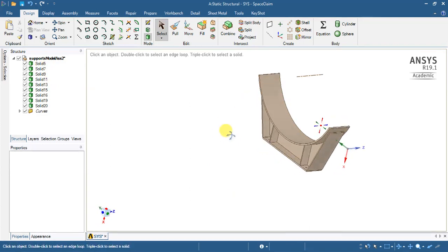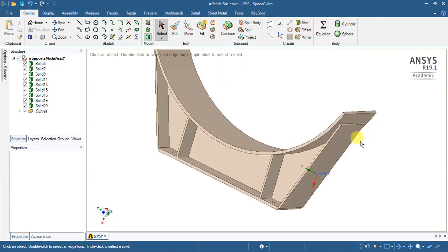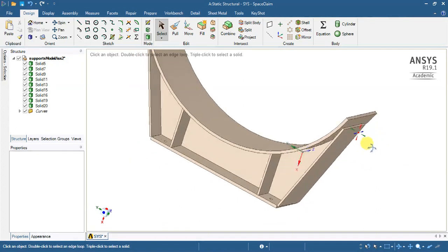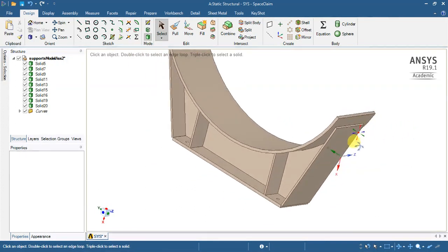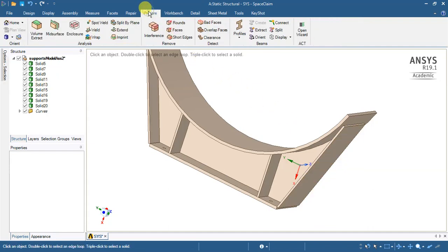Okay, so now we're going to work with one of these. What he did in class is he said that it starts out with actual 3D blocks, and I'm not sure why we delete it or what the reason is, but we're basically going to make these into mid planes. So we're going to draw a line, find the midpoint of it, and draw a line using a feature. The feature he uses is in prepare, and it's called mid surface at the top left here.